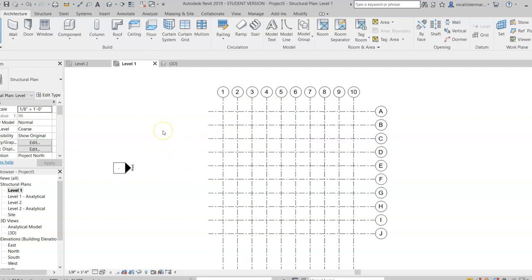So this is a great way to start your framework with any drawing design that you're going to use in an architecture or a civil engineering class, because it gives them that XY system. I reference it a lot like putting stakes in the ground to put in concrete forms, and also for placing columns and exactly where everything goes. So this is a really good way to start your projects in Autodesk Revit. This has been a video on how to create vertical and horizontal grids and use rectangular array to place them in Autodesk Revit.